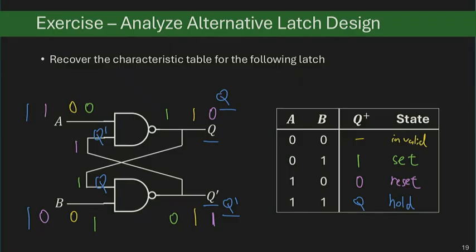Essentially a number of tricks. I'll just sum it up. Number one, use a smaller table. And in this 1, 1 case, if you want, you can partially expand that case by using concrete values on Q: Q equals 0, Q equals 1, and so on. But I like to do this kind of symbolic evaluation. Number two is when you pick a particular input combination, start with the side that dominates the gate, so you can run the evaluation regardless of the previous state. And that typically helps you to simplify the problem.